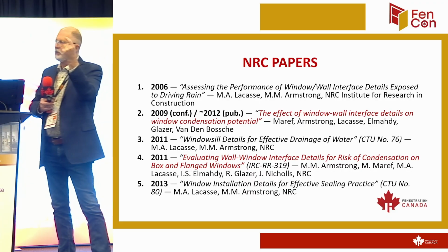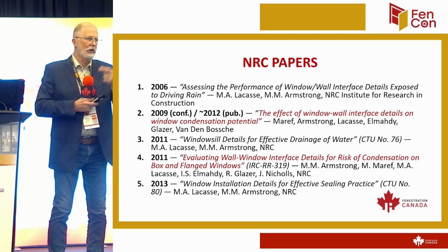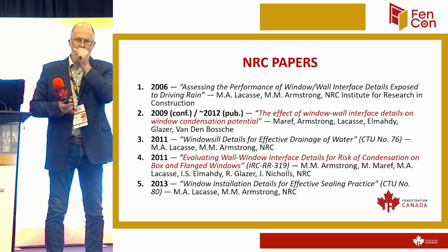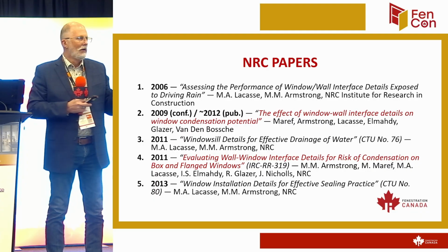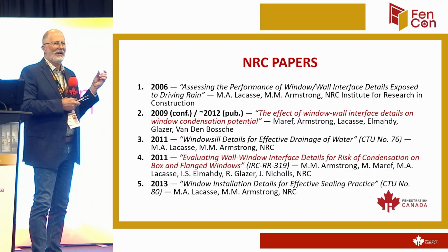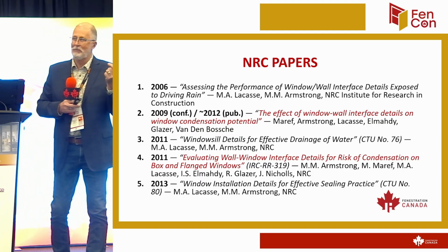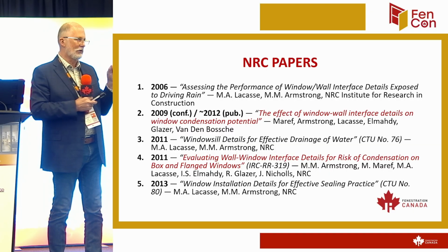So between the one with no insulation to the one with fiberglass, what do you think the temperature difference on the inside of the frame would be? A couple of degrees? What's that? Less than that? How about half a degree? Their instrumentation wasn't accurate enough to test it, but they came up with half a degree. When they moved to spray foam, the temperature difference was 1.5 degrees.